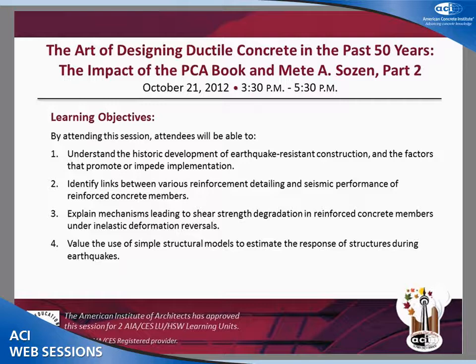Some of them have already been discussed in the first session. But we have, first of all, the development of the most widely used hysteresis model for simulating the behavior of reinforced concrete structures in earthquakes, which is the Takeda model. The use of equivalent damping and the substitute structure method, which was the topic of the very first presentation in the first session, and its application to displacement-based design and performance-based earthquake-resistant design for limiting damage during earthquakes. Understanding the mechanisms of shear strength degradation in reinforced concrete members with displacement cycles, and the development of methods for a rapid evaluation of vulnerability of structures during earthquakes.